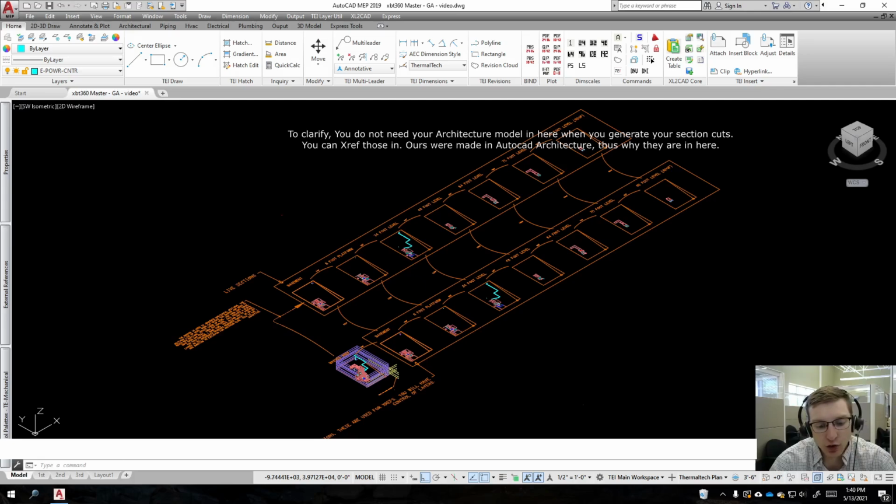Additionally, now you have to have a strategy for maintaining the original 3D model that makes up the multi-view part. So you have to save that separately because you really can't edit most multi-view parts. There are ways to, and I do outline them in some of my other videos, but I'm not the biggest fan of those. However, if you do make a multi-view part, global cut planes will work. So this strategy that we're going to show you here is for if you have equipment and you don't want to convert everything to multi-view parts. This is a workflow that you can use.